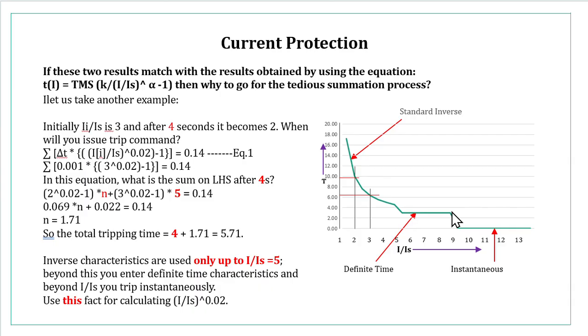Here current is very high, but still you are in a position, you are willing to do some waiting. You know, when this situation arises, when you switch on a motor, then the motor takes almost 6 to 8 times the current. And so if you don't provide sufficient delay, the relay will trip it directly. So you switch on a motor and the relay will trip it. Again you switch on the motor, relay will trip it. What is the use of having such a relay?